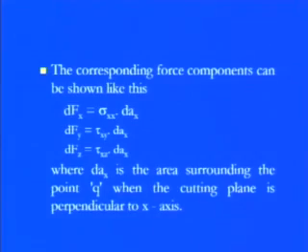Similarly, if we have chosen dFz, in which we also see tau xz, x is the domain in which the force is there, all the segments are there, but the force is going in the direction of z. So we have the shear component here. So if we have chosen a small point just in the x domain, we found that there are three varieties of stresses: one is sigma xx, tau xy, and tau xz. So these three forces are there in the x domain.